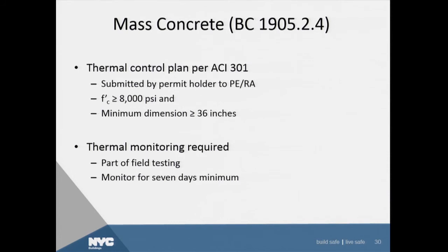The committee also made some enhancements with the advent and the greater use of high-strength concrete greater than 7,000 PSI. I still come from the days when, practicing, you had to write 5,950 PSI as your design strength on the drawings because nobody wanted to touch 6,000 PSI or higher. These days, you can easily see on many high-rise buildings 8,000, 10,000, 12,000 PSI being used.